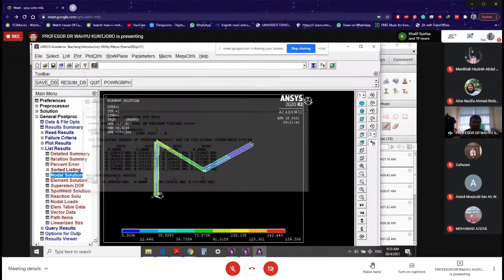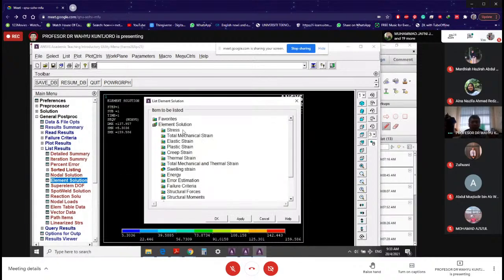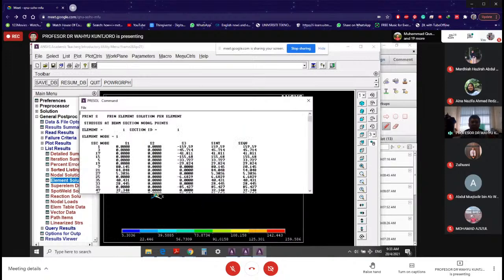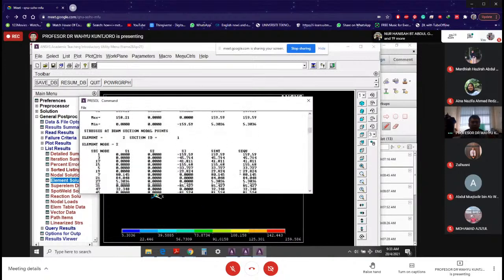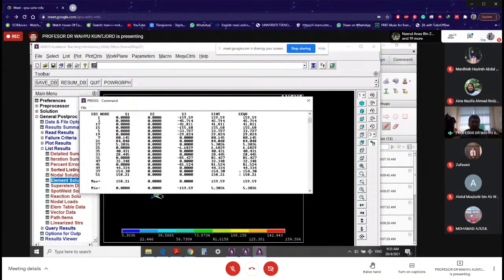All right, so what about the stress? The same. You can go to element solution. You can find the stress, von Mises, for example. And that's what you have at every element.